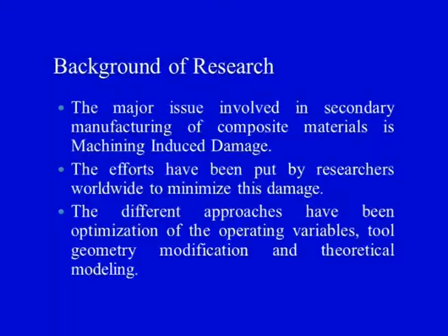So, researchers worldwide have tried to develop the theoretical models also, which in a way try to minimize the work of the scientists and the engineers by providing ready-made tools which can help to predict the damage and the forces which can be generated during the drilling of polymer matrix composite. So, the research work is going on towards minimization of the machining induced damage, and some of the focus areas of research have been highlighted. Those are the optimization of the operating variables, tool geometry modifications and the optimization of the tool geometry, and the theoretical modeling.